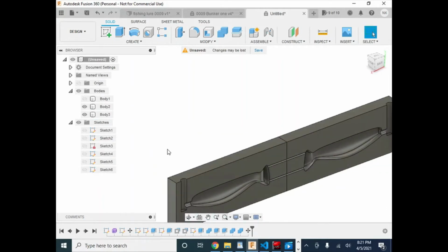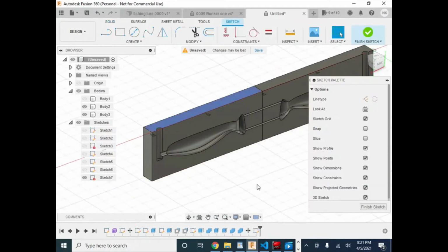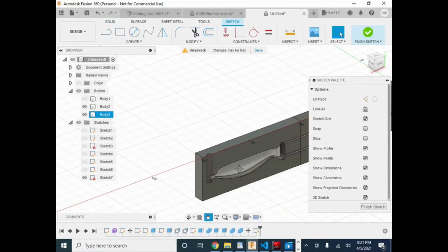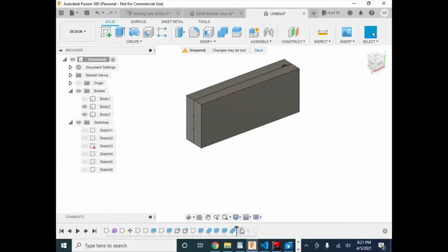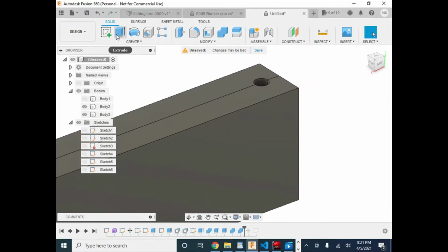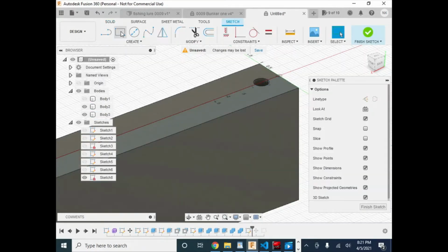Like I said before, if you have an injection port, let's just go ahead and do that real quick. What I like to do is create a sketch and pick this plane. One of two options: either we roll back before we moved that item, so we'll go back to here where we can see it. Again, sorry, create a sketch. We'll just pick this surface as our sketching plane.